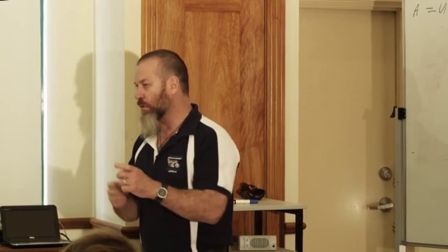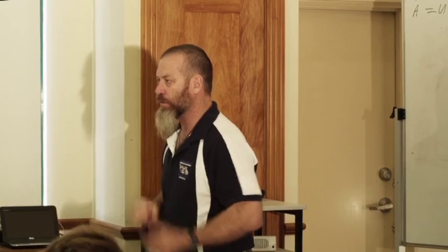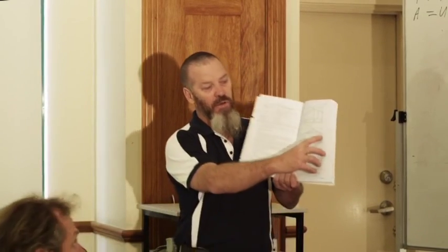That's a stick roof. If you have a look at that second diagram on the right-hand side, think about what I said about connections and not spacings. This rafter is connected at the top plate and its next connection is where it meets the underpurlin. Can you see that?